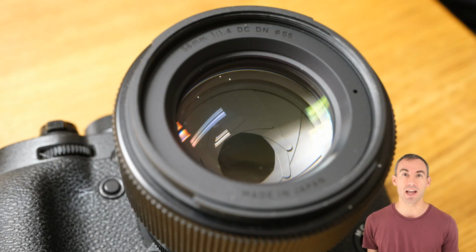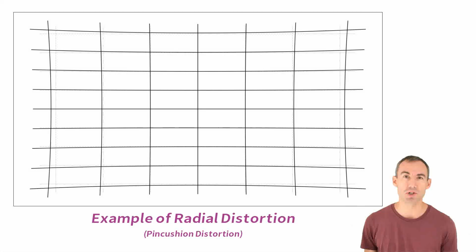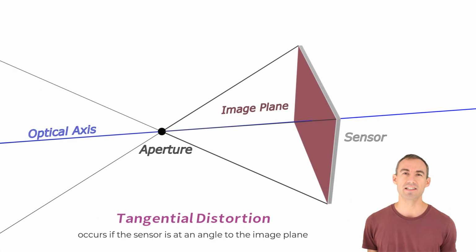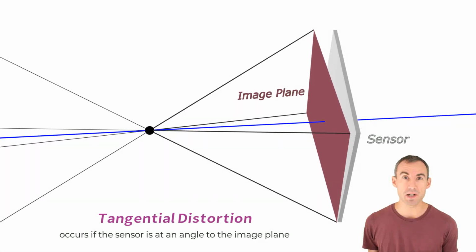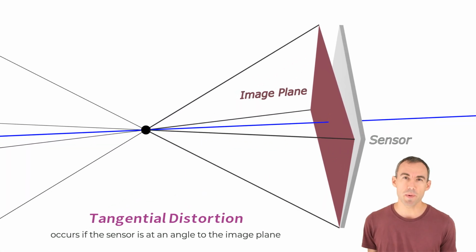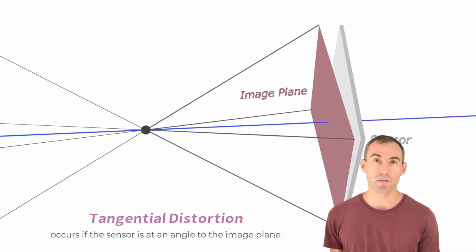But lenses introduce errors, for example radial distortion or tangential distortion, and those errors are not captured by the pinhole model. So if we use the pinhole model for real cameras, then we make errors. But some of those errors, like radial distortion, can be corrected at some later point, and others, like tangential distortion, are so small that we can usually ignore them if we use a good camera and lens. So the pinhole camera model is very useful because it's simple and reasonably accurate.